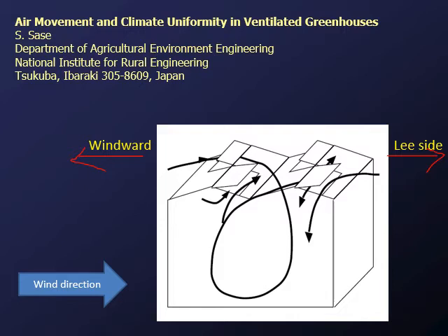Now, why this is important is because typically the vents that are facing the wind, which is the windward, so these ones, open less. So you have a smaller gap on this side, and the ones that are facing away from the wind have a larger gap. And that sort of allows you to scoop a little bit of air, allow this exchange, and create a negative suction to pull it out the top.